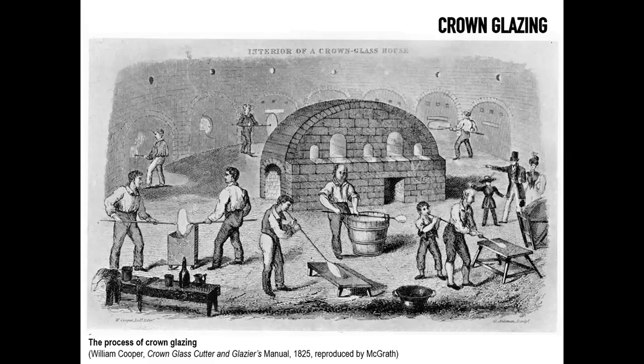Now, crown glass is a term that was introduced because one glazing manufacturer in England used to emboss the center of the glazing panels that were produced with this method with a crown, so that the terminology somehow still sticks to this date. Now, the system was very simple in intent. So the lump of glass would be extracted from the furnace, it would be gathered, and then it would be spun to transform itself into a disc. And then this disc would be cooled down and then eventually cut to pieces to be used for window panes. Now, this is easily said.